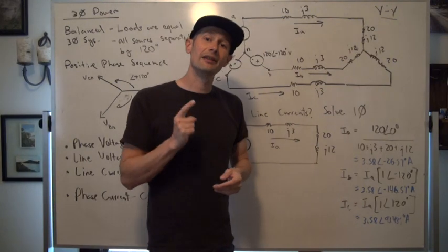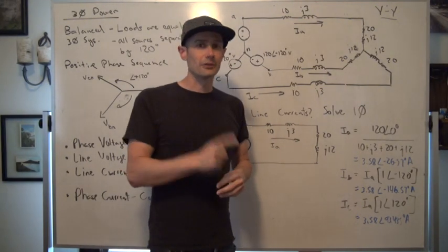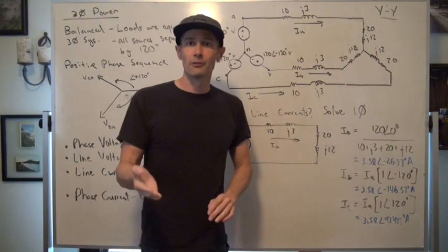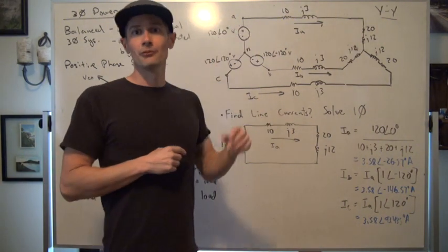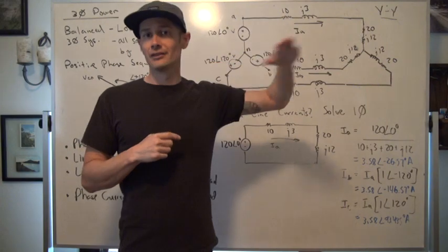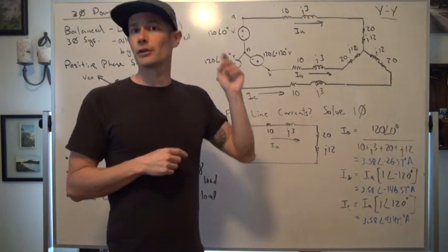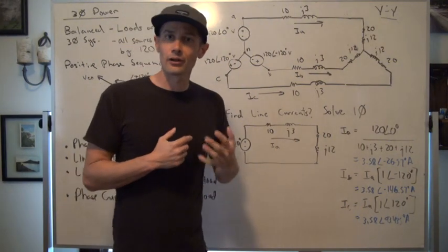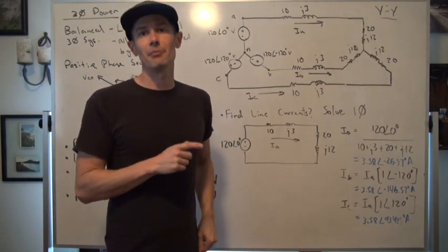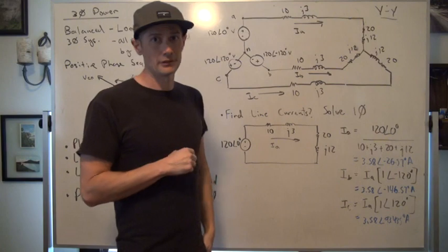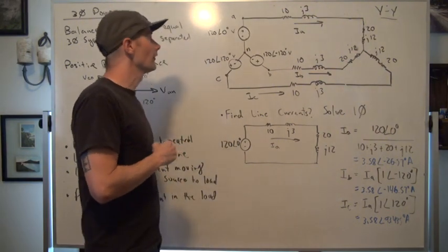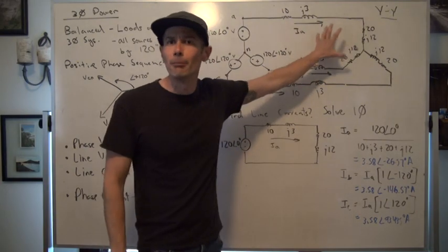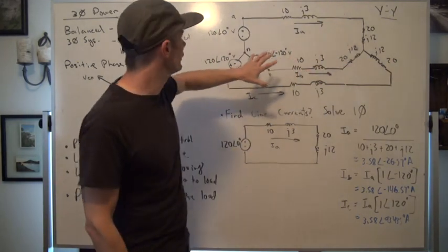What that means is that every voltage and every current, from phase to phase to phase, no matter what we're solving, whether the current in the line for a phase, the current in the load for the phase, or the voltage in a load for a phase, are all separated by 120 degrees apiece. Now, this is generally what a good model of a three-phase system looks like.